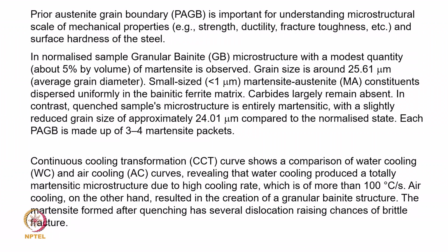In the quenched sample, the water quenching sample, what we find is that the matrix is entirely martensitic, with a slightly reduced grain size, maybe 24 microns as I mentioned, and even the PAGB, which is the grain boundary, will consist of 3 to 4 martensite packets.